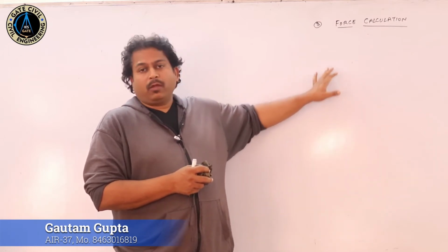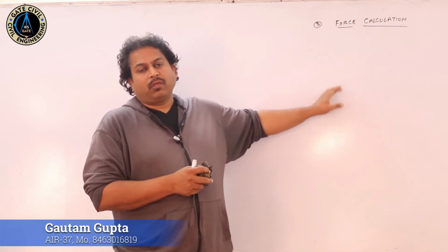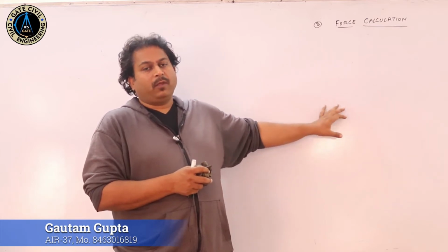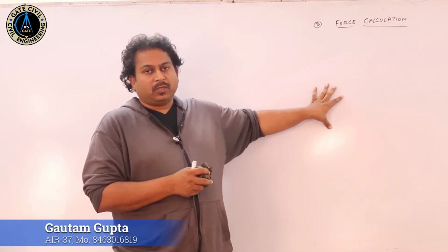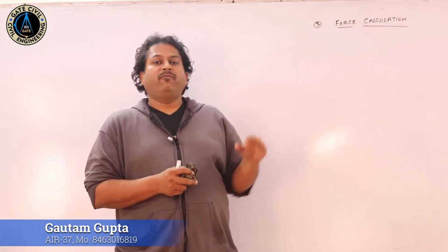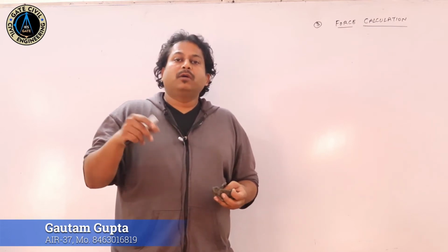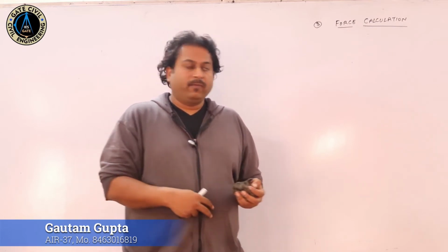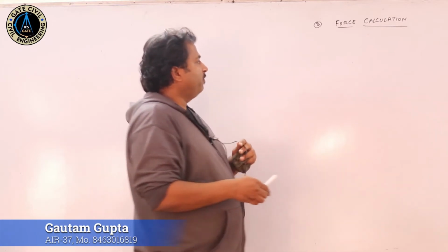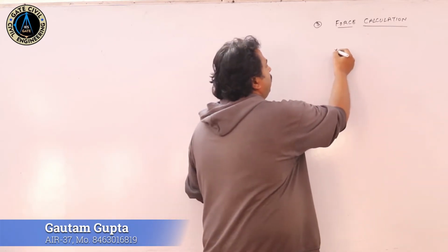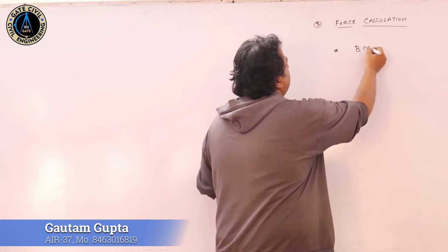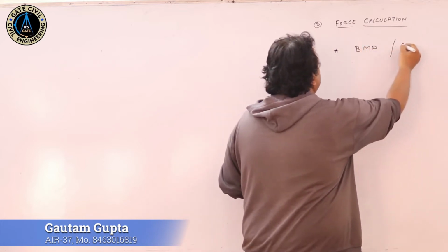So we will be drawing and calculating the forces, BMD, SFD, everything based on the unfactored condition. Later on, when we will be doing the moment or the shear check, we will be adding the load factor of 1.5.